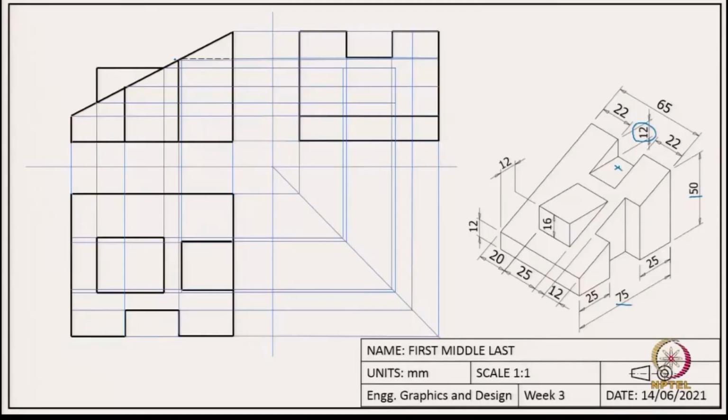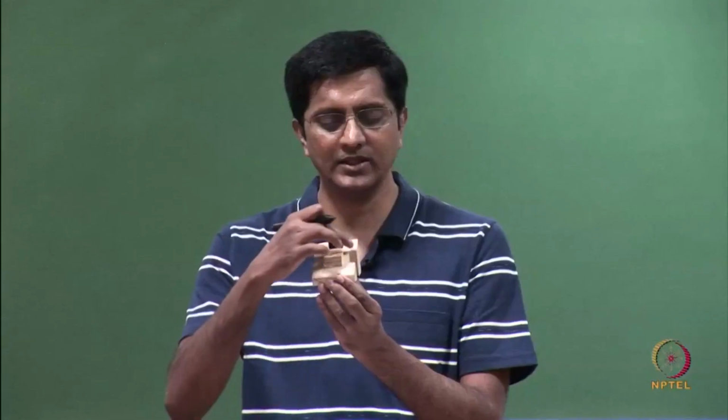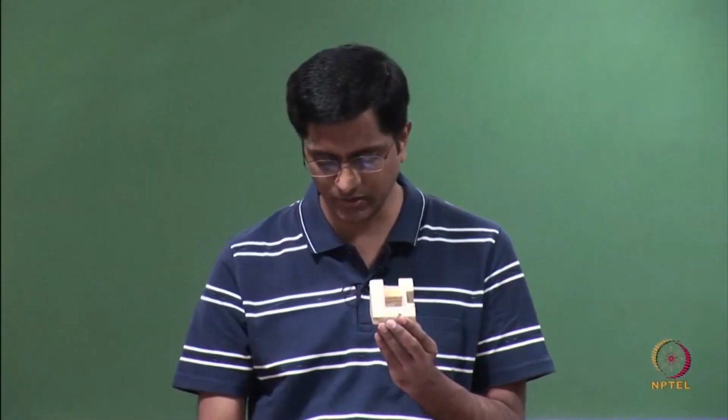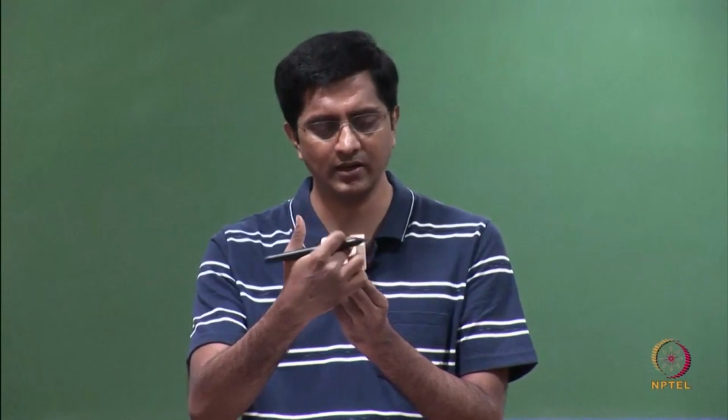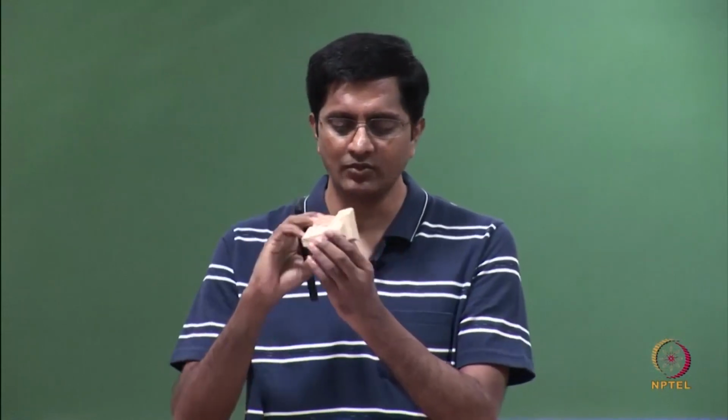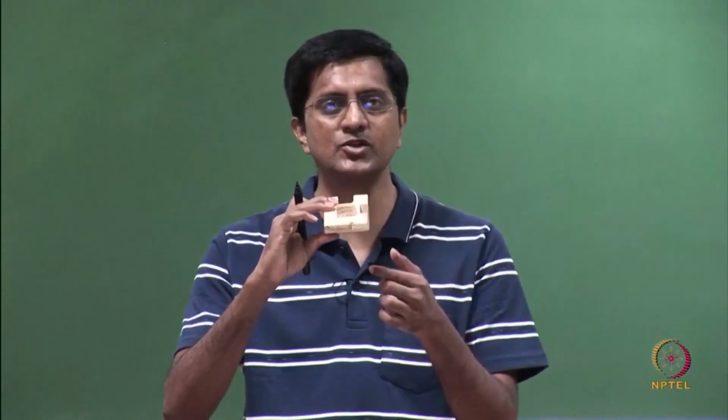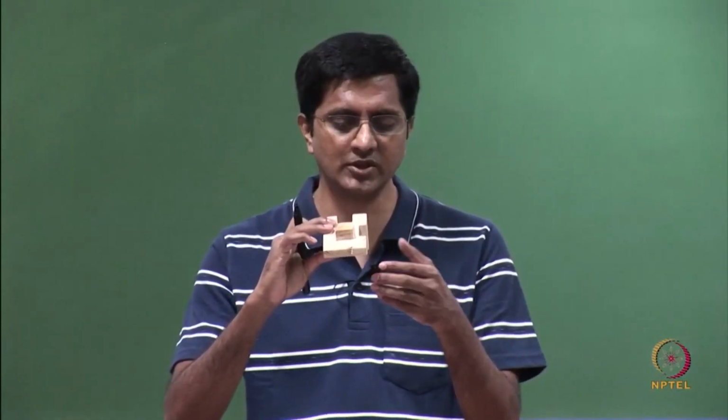Again I use the information from front and top view to draw this rectangle. And lastly, these features. So, again I use the projection lines to draw this slot. So, this slot I will first look at as a small piece of rectangle, and lastly, for example, this edge you can't see it in the side view, but that needs to be represented. How do we capture that?